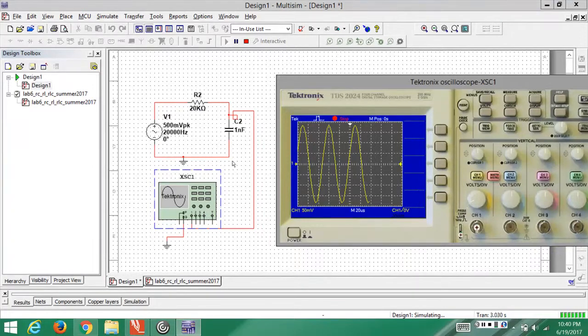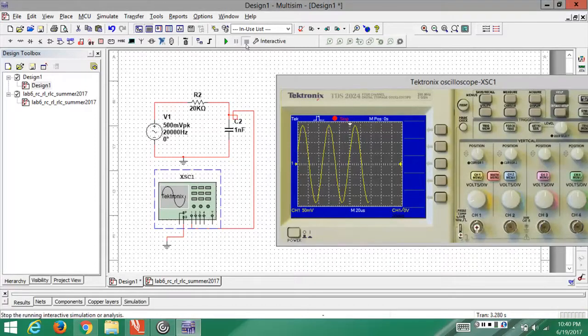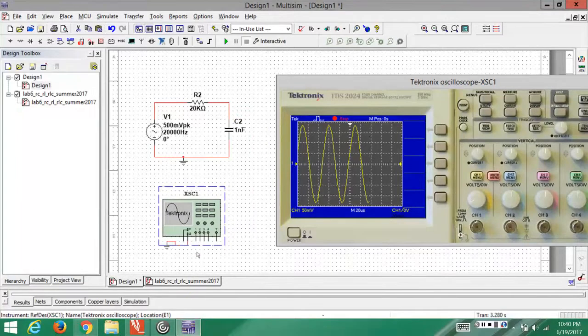But when it comes to this resistor R2 and we do the same kind of setting, that is, we connect channel 1 from here. This voltage reading being taken at this point is basically the same as taking the voltage reading across the power supply, because the voltage drop here is going to be the same as the voltage reading for the power supply source.